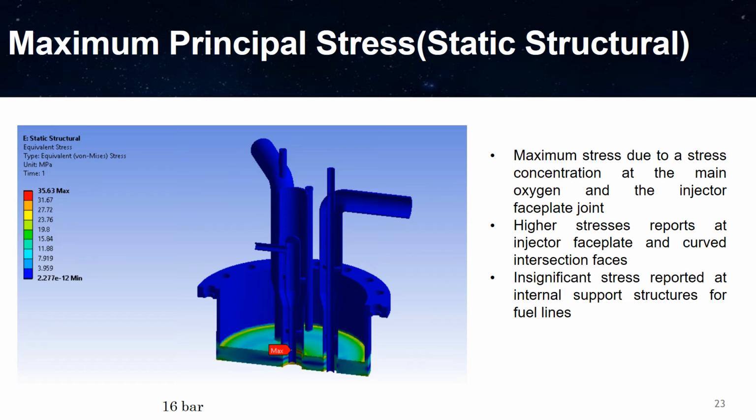And the highest stress is 35 megapascal, which is basically at a stress concentration region. So we're not very concerned about the stress concentration, but if you look at overall stress, it is reasonably low on the injector face during 16 bar.